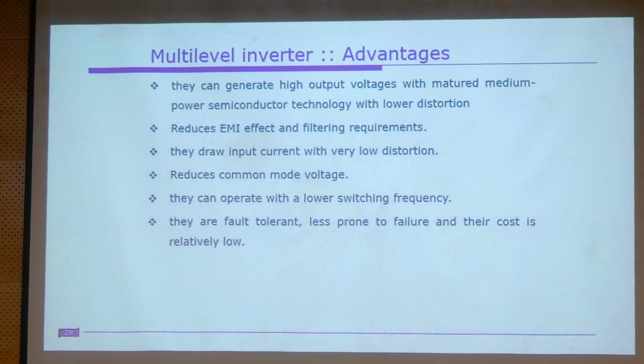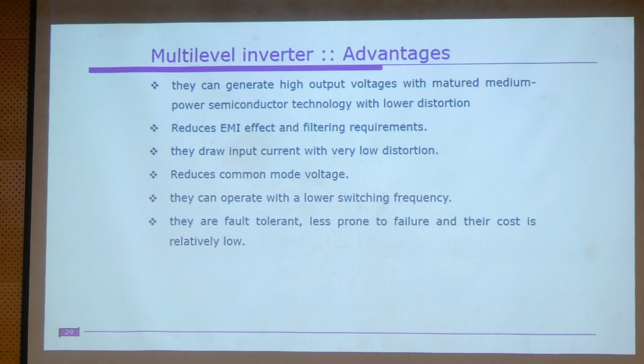If the current is more, what happens? That leads to higher losses, right? Especially if there is current flowing between the stator and the motor, or the stator and the rotor parts, or some moving parts, inside there will be some bearings or some materials which are used as a lubricant. As you are increasing the heating, the lubricant's chemical properties will be altered, and due to that, the life expectancy of that motor will be reduced, right?